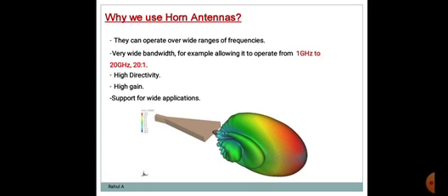That is, we can say the loss is very low. So whatever power we are transmitting, almost all of it is getting transmitted in free space in only one particular direction. Because of that, the higher gain is achieved, which is hardly possible with other antennas like the Yagi Uda antenna, where the power is transmitted in almost all around directions. But with the horn antenna the case is different, where we can achieve a higher directivity.